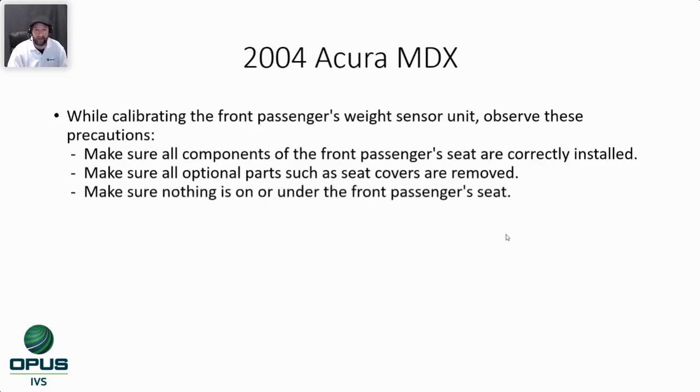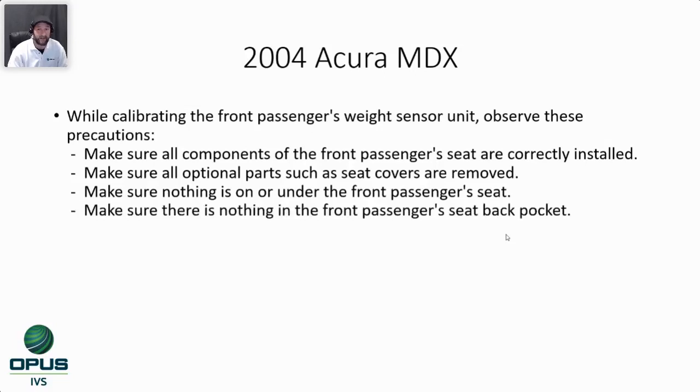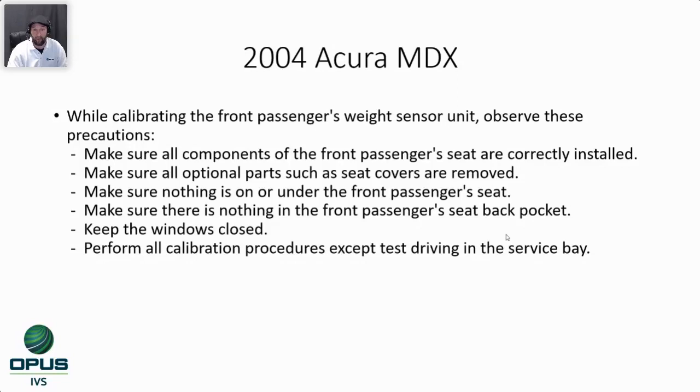So make sure that nothing is on or under the front passenger side seat, nothing in the seat back pockets, keep the windows closed, perform all the calibration procedures except test driving within the service bay. They had to tell us that, just in case you were thinking about test driving in the service bay.